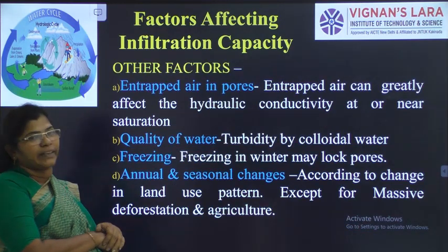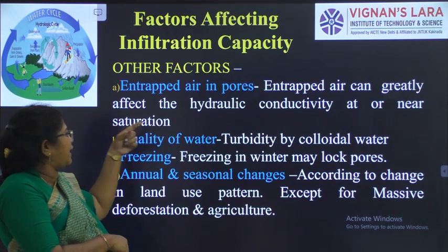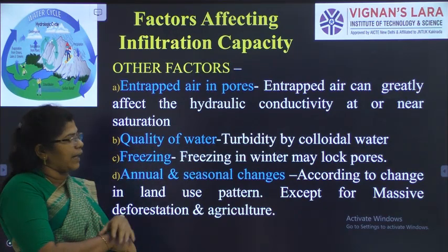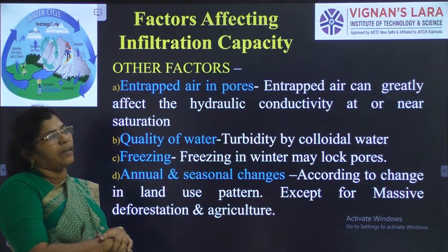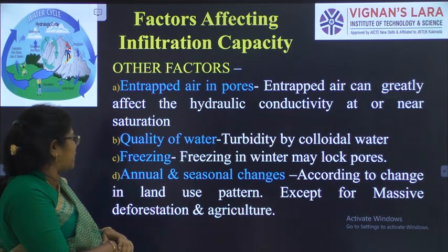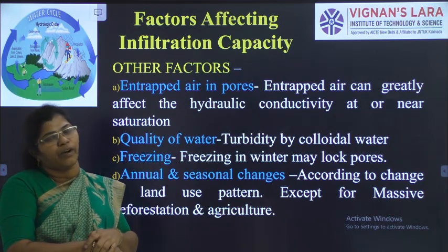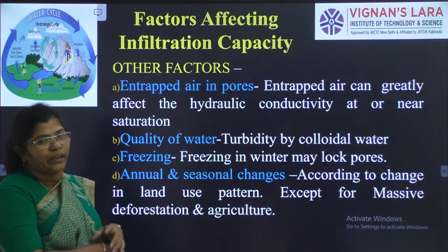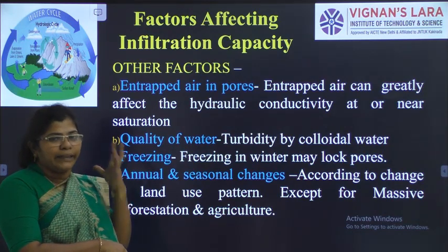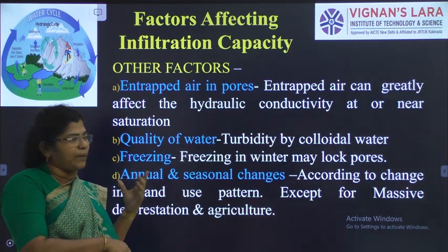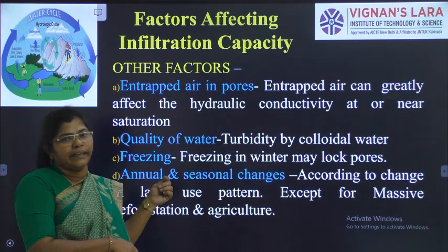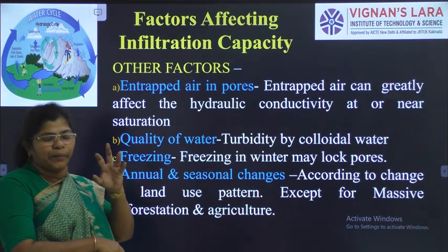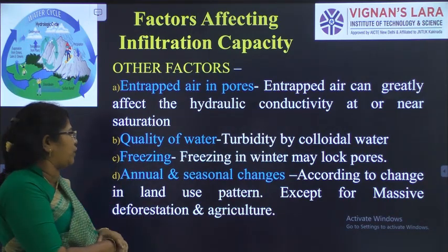What are the other factors that affect infiltration? Entrapped air in pores can greatly affect the hydraulic conductivity, by which the infiltration will be less. Quality of water: if the water has more turbidity, colloidal matter, dirt and other impurities, it cannot be infiltrated into the sand.